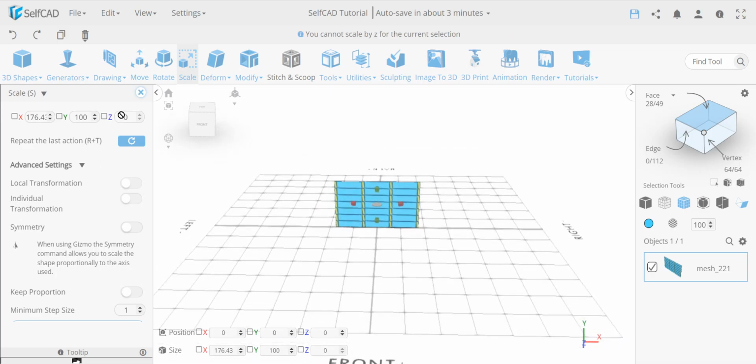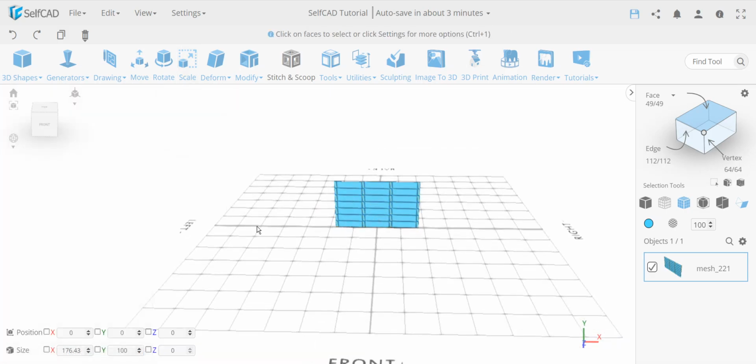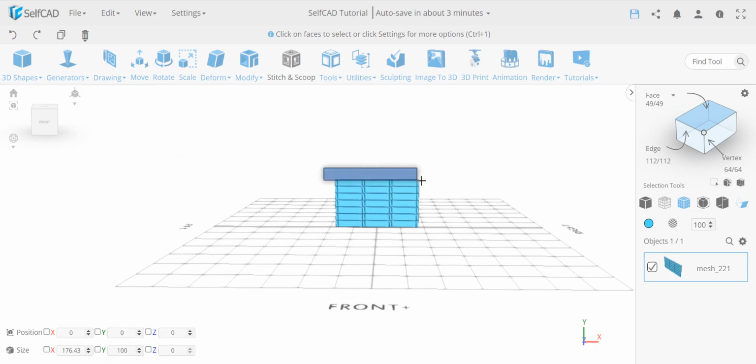Okay, now what we'll do over here, I'm going to select the same thing but in the other direction. I'm going to select the pattern over here. Now you see I actually use the marquee selection. You can use it simply by using your mouse, drag and drop, or you can turn it on from here. There's an option marquee selection, and it's the same thing. Now you can just left click, I don't have to right click. Normally without this turned on, I have to right click to drag. And with this turned on, I can use the left mouse. This is basically my key selection.